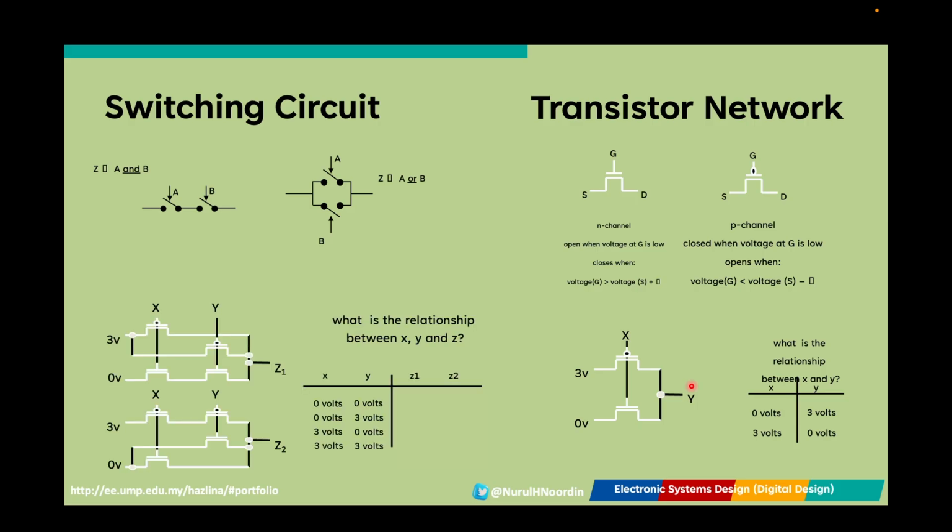Likewise, the switches could be arranged in parallel form, and form different gate functions as follows. The speed of CMOS network depends on charging and discharging of voltage on wires and gates of transistors. Capacitors hold charge; capacitance is at gates of transistors and wire material. Resistors slow movement of electrons; resistance is mostly due to transistors.